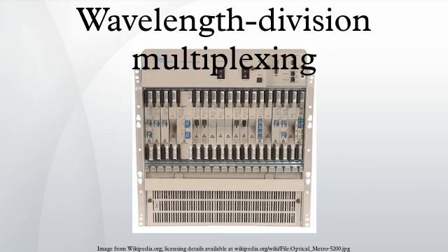WDM, DWDM and CWDM are based on the same concept of using multiple wavelengths of light on a single fiber, but differ in the spacing of the wavelengths, number of channels, and the ability to amplify the multiplexed signals in the optical space. EDFA provide an efficient wideband amplification for the C-band. Raman amplification adds a mechanism for amplification in the L-band. For CWDM, wideband optical amplification is not available, limiting the optical spans to several tens of kilometers.